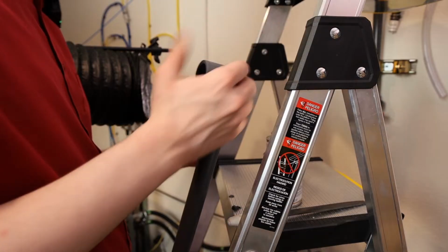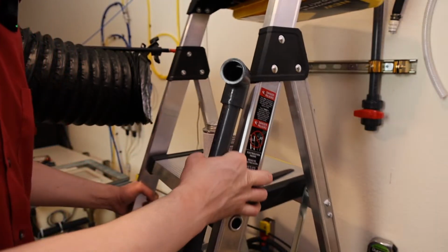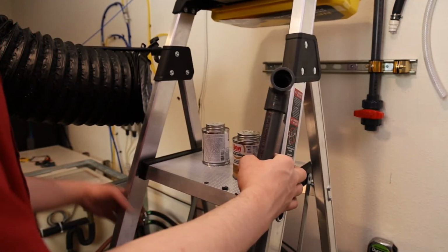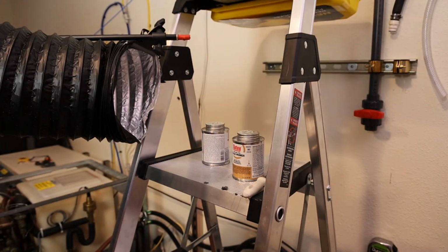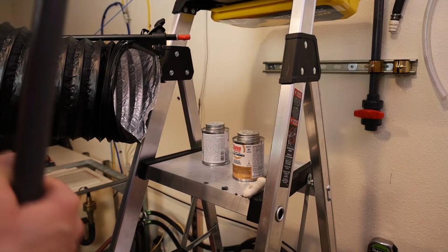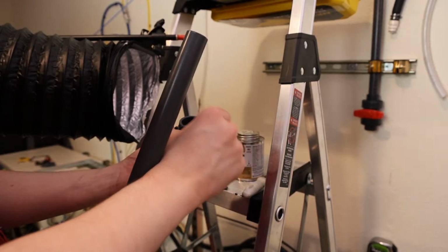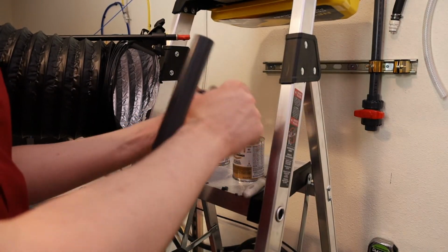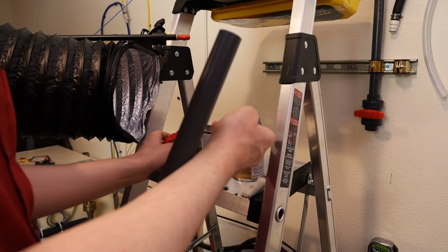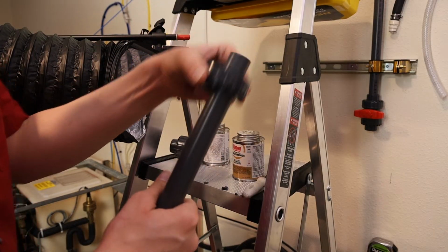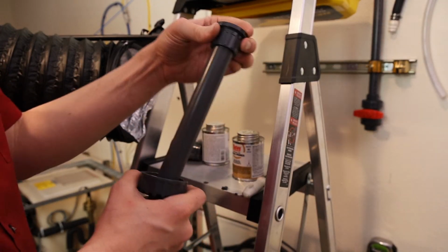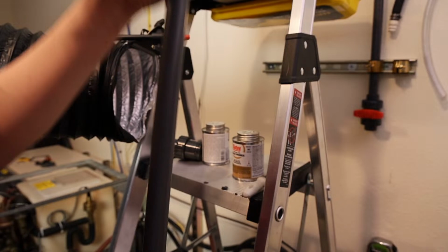Well, actually, I don't know why I'm moving all this around, because we're looking at the other end now, too. The other end is a union, because it's a union valve we're using, so we can just take off one of our ends here. And very, very important that we remember to put this part onto the pipe in the correct direction, or we are going to regret that later.